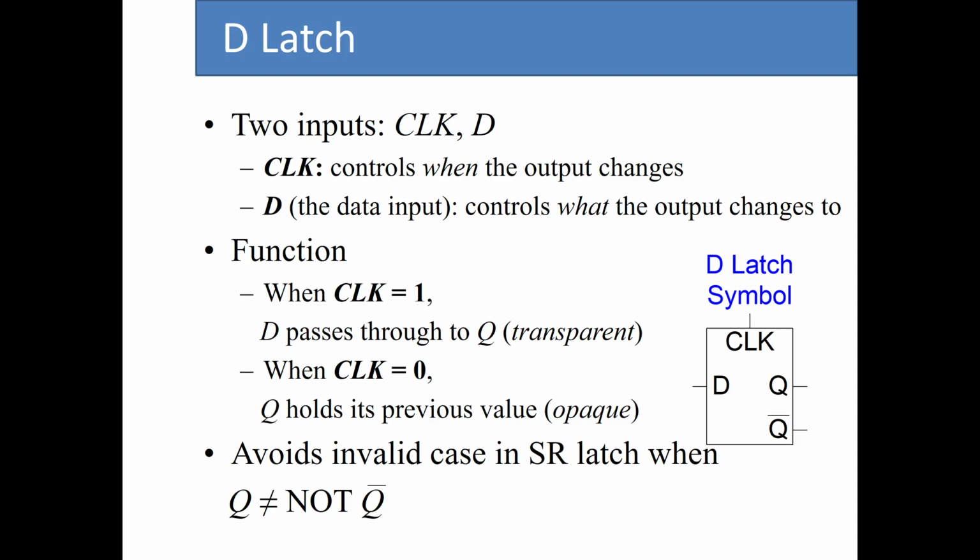More specifically, something that was not that obvious with the SR latch, but when you talk about the concept of sequential circuits, there is an element of time involved as well. With the SR latch, there was no element of time. We had a set input and a reset input. There was no time input. So for the D-Latch, we want to avoid all the problems of the SR latch.